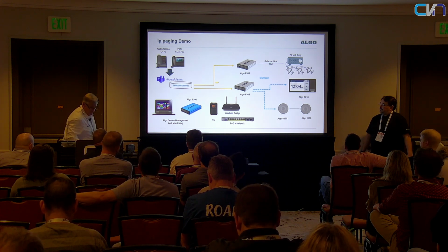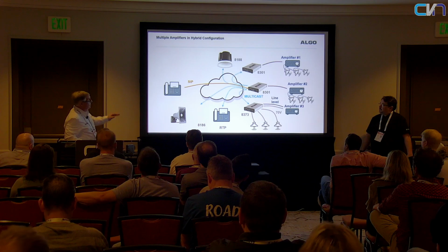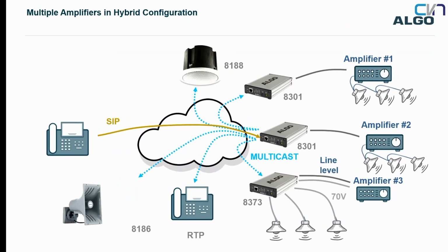So what we'll do, and this is very typical, I like putting this slide up. This is a slide that brings it all home for me. This is an example of what's going on at that airport. I'm doing a single SIP registration to a device, and that device is going to answer, and my voice will come out onto amp 2, because I'm physically connected to it, but I'm also going to multicast onto the network, and I can broadcast to all those amps and speakers, and you'll notice RTP.